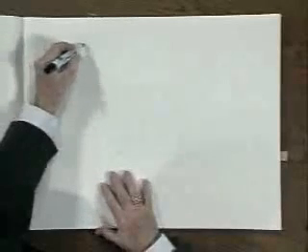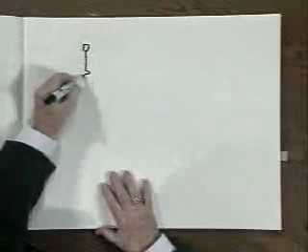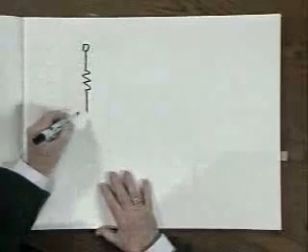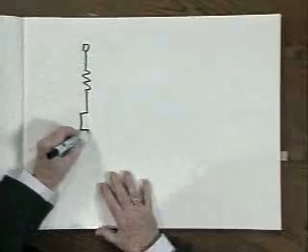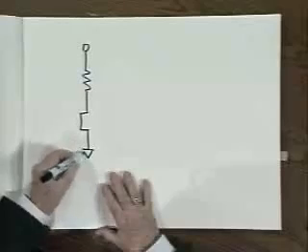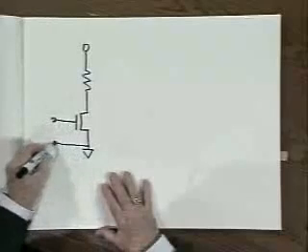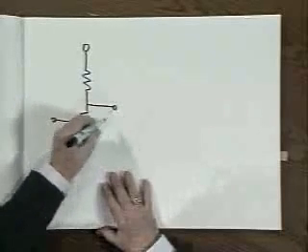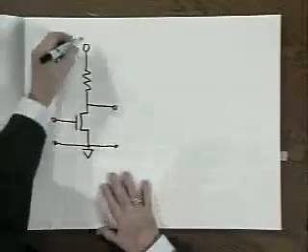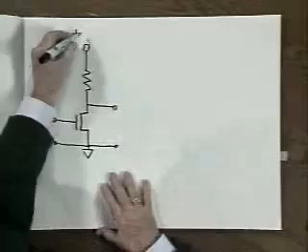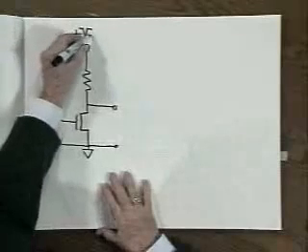Now, if we put the transistor in an amplifier circuit, it looks like this. This is the simplest kind of transistor amplifier. It's called an inverting amplifier. A pair of input terminals there, and a pair of output terminals here, and a supply voltage up here, which I'll just represent as plus V sub S.